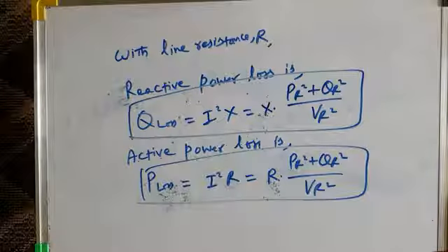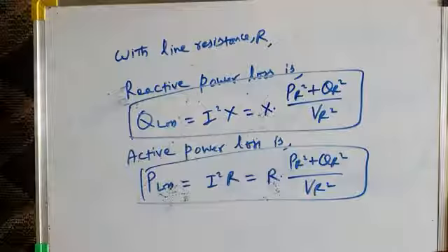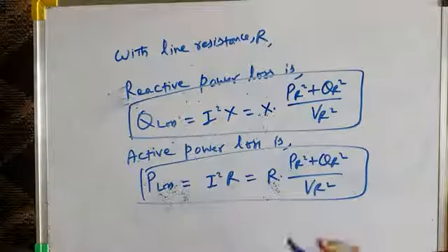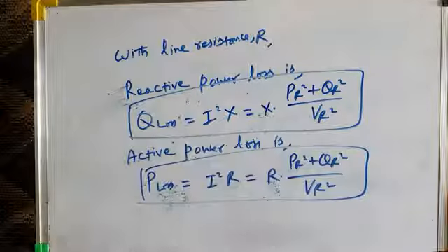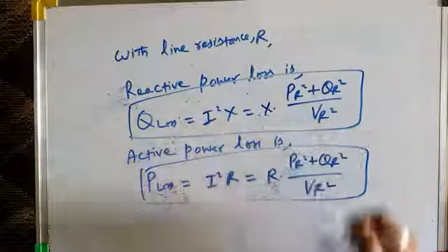So one very important thing you have to remember: generally the active power flowing over a transmission line, let us assume, is constant depending upon the load, but load reactive power may change depending upon the load power factor. During a particular time of the day when most of the industrial load is switched on, the power factor may deteriorate, and reactive power demand may increase.